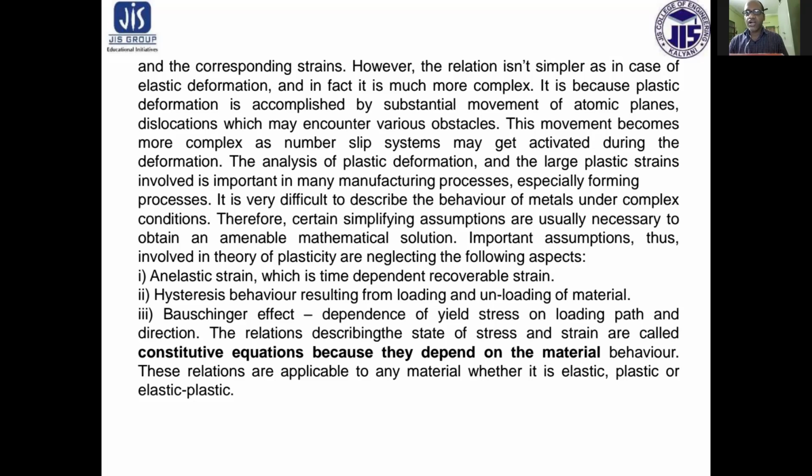It is very difficult to describe the behavior of metals under complex conditions. Therefore, certain simplifying assumptions are usually necessary to obtain an amenable mathematical solution. Important assumptions involved in the theory of plasticity are neglecting the following aspects. First of all, anelastic strain, which is time-dependent recoverable strain. Number two, hysteresis behavior resulting from loading and unloading of material, and Bauschinger's effect.